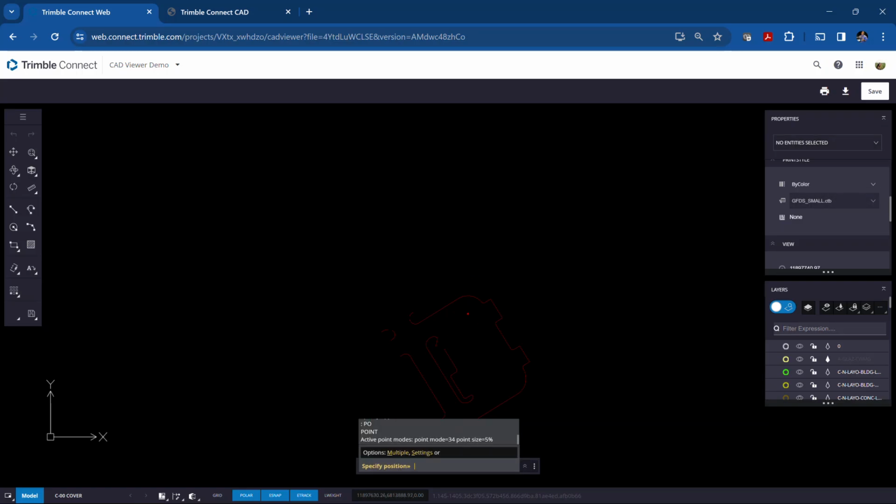Now remember, your coordinates are X, Y. Your northing is your Y, sorry, and your easting is your X. So even most people when they say northing easting, make sure you put it in correctly, otherwise it'll be flip-flopped.